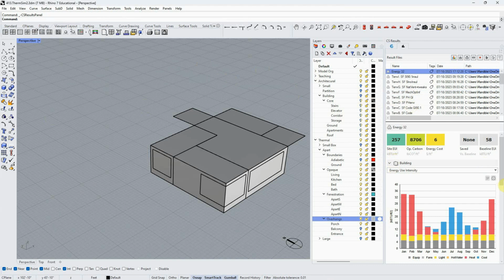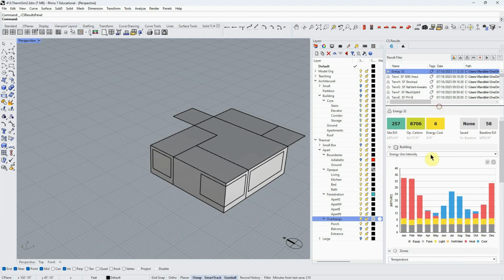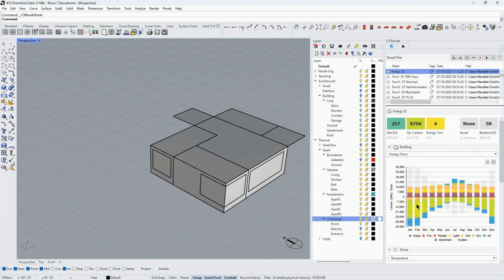And here's my results. So sort of ignore this actual number in terms of the baseline here. This baseline is set for a medium office because there is no single family home. So anyway, we're just learning the workflow here. We're not really trying to get something accurate. But we have obviously a lot of work we can do. We have really large losses in the envelope. The windows, once we get this under control, we'll look at because they'll have more of an effect.